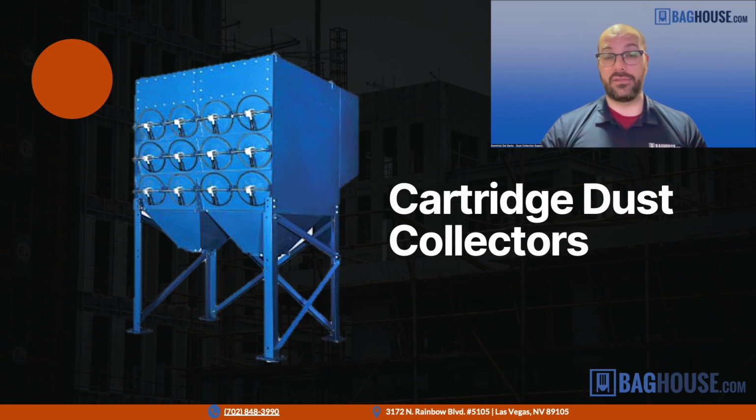Now, the downside of this is that because it's all jammed on there tightly, it's a little bit more difficult to clean the filters, and they can't quite handle the same dust loading, or the amount of dust coming in, as the baghouses. So we often use the analogy that the baghouse is like a big heavy pickup truck that you can do everything with.